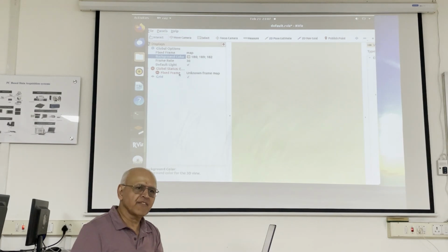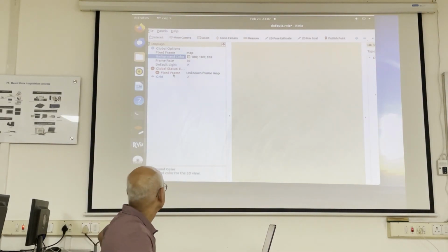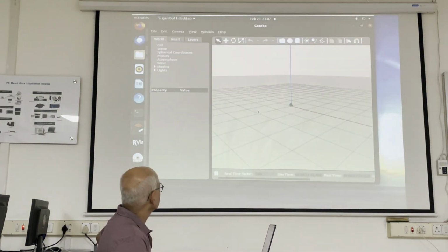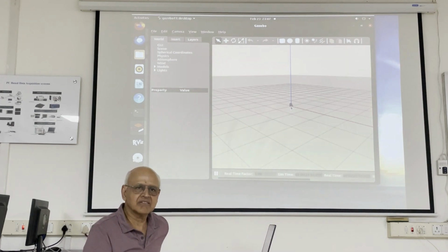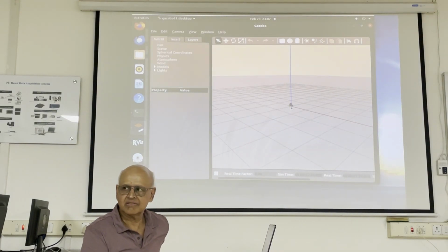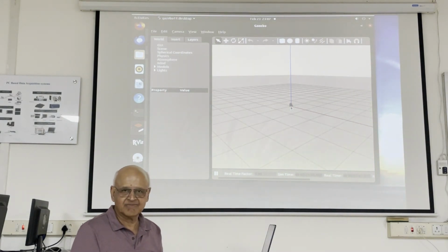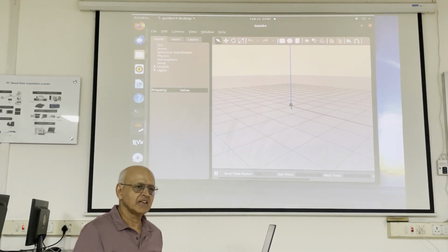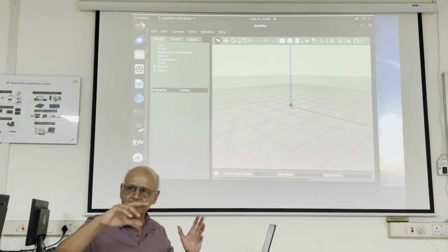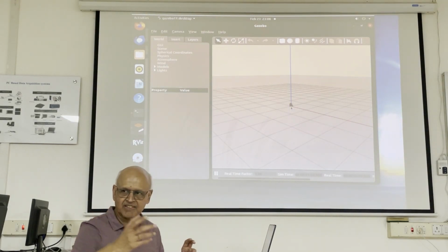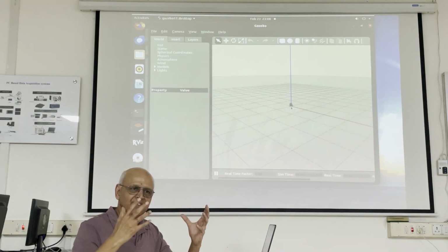So the most important fixed frame is the world frame. But we're not using that as a reference here. I just wanted to mention that this right here, see here, blue, red, and green, this is buried in the ground at 0, 0, 0. So that is the most important fixed frame. It's called the world frame. Now, if you're doing something with Mars, you can have a frame there also that is fixed, right? But there can only be one absolute world frame.